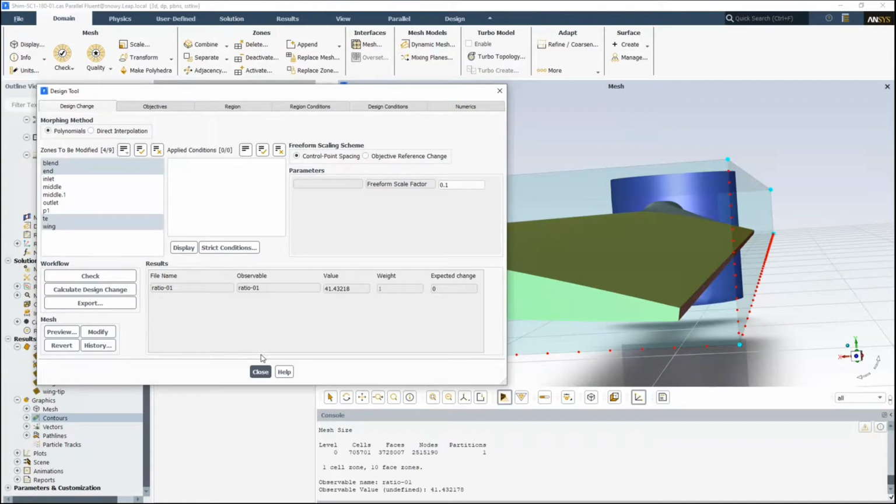Okay, you're solving for the derivatives of those solutions, those observables at each point on the surface. And what that means is you're getting a linear approximation at that point. CFD is highly nonlinear, so when you actually move the mesh, if you move it too far, you may not get the expected behavior change because you're calculating a linear derivative at that point.